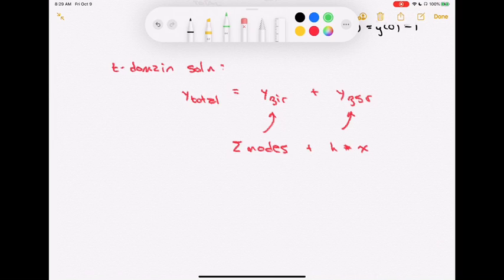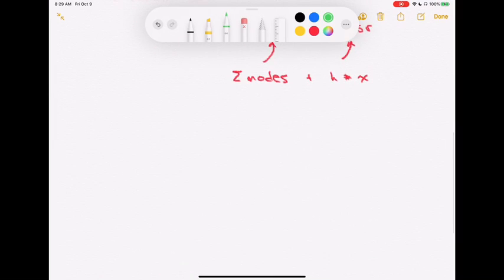What we would like to do instead is engage in a transform domain or a frequency domain. So I will call this a transform domain solution. Let's go ahead and look at the transform domain solution instead. I think this one should be a lot easier. Basically what we're going to do is employ the unilateral Laplace transform. The reason that I would like to use the unilateral Laplace transform rather than the bilateral Laplace transform is because I have initial conditions that I need to be incorporating into my overall solution.